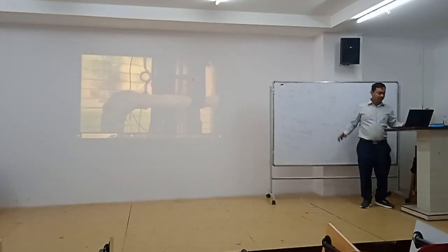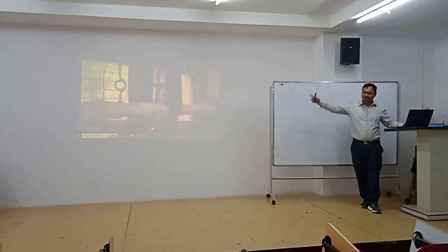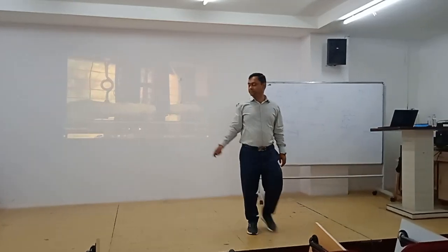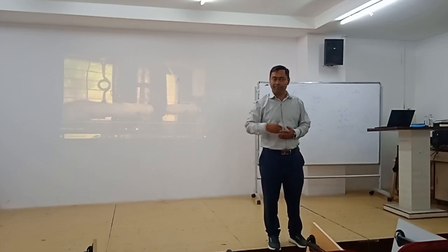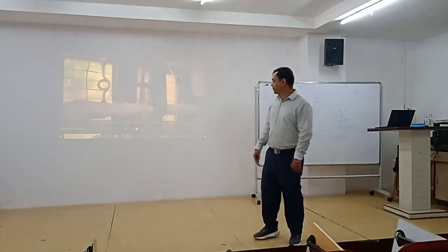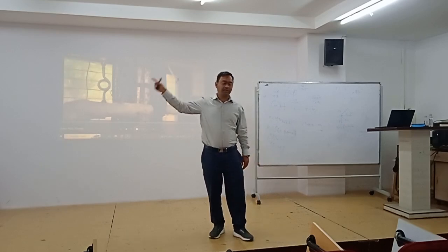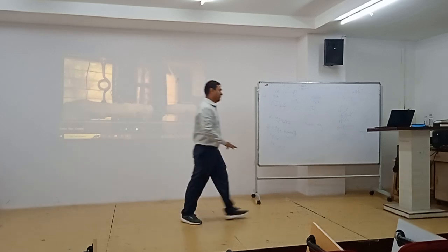So this is the pipe. On the pipe you can see some white cloth because internally we have kept a heater also. This equipment is made for a variety of purposes. We can control the flow, the temperature, and the motor speed. When we go for temperature control, the temperature may go to more than 100 degrees. That's why this white cloth is for thermal insulation.